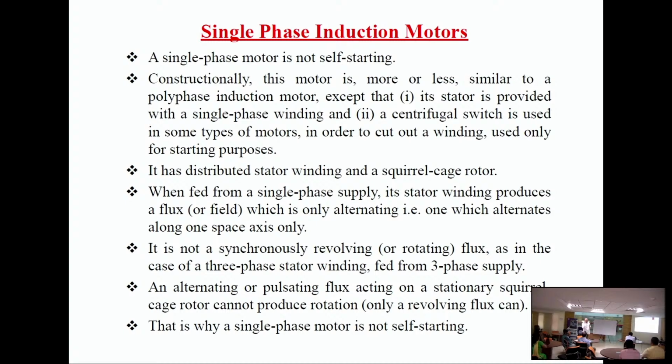Why is the single phase motor not self-starting? Because a single phase supply cannot produce a rotating magnetic field. That is the answer. If a rotating magnetic field is produced, then similar to the induction motor, it will start. It cannot produce a rotating magnetic field.